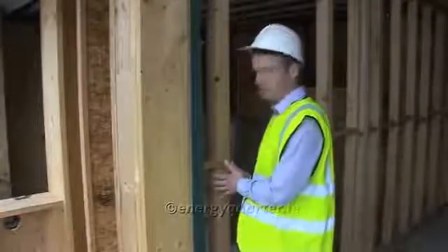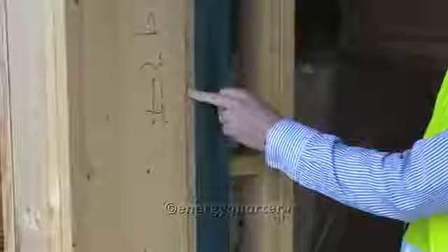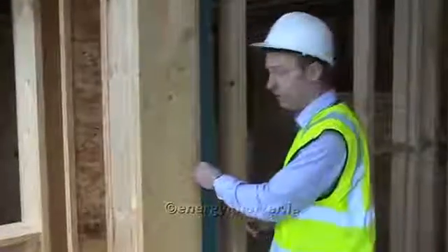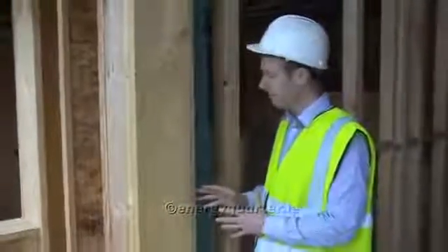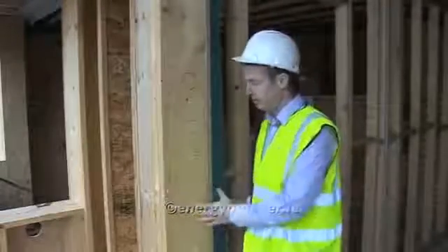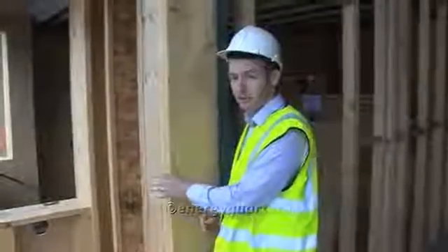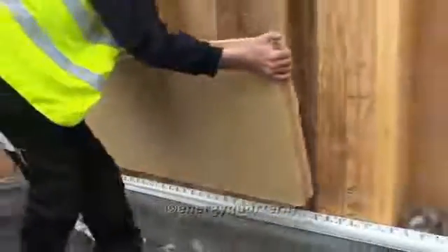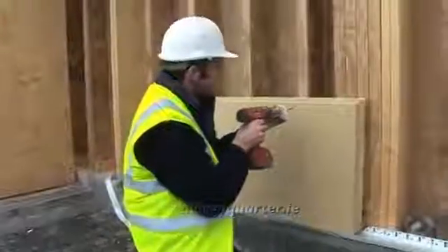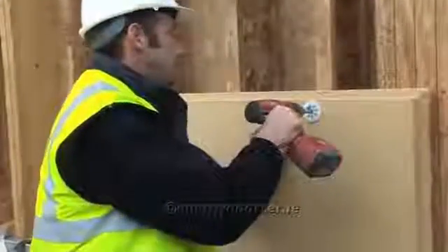On this passive house, the wall build-up will be as follows. There will be a gypsum plasterboard on the inside, then we'll have a service zone with 80mm of thermohemp. Then we'll have an 18mm OSB board. This will act as the airtightness and vapour control layer, which will be taped and sealed with the ProClima system. Then we have a 241mm thick I-beam stud, which will be filled with blown cellulose paper insulation. Then on the outside of these walls, it will be insulated with a combination of either an 80mm thermowall board, which will be plastered. This is a Gutex wood fibre board, or alternatively an 80mm Gutex Ultratherm board with a ventilated cavity and an external covering.